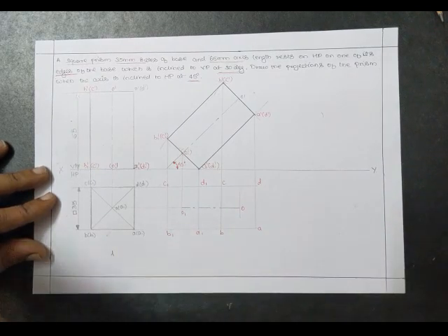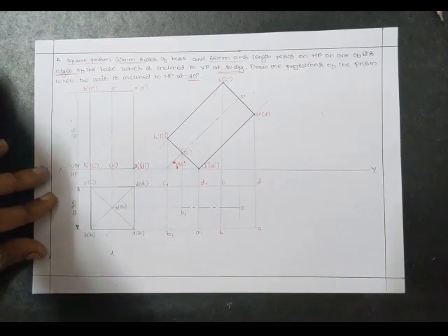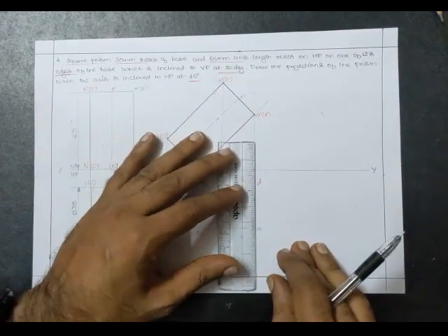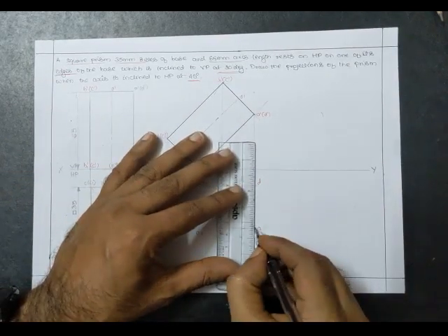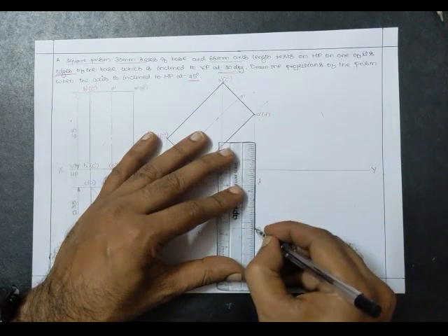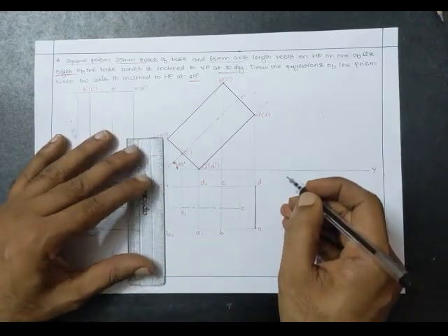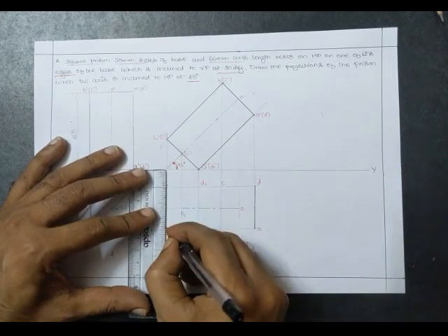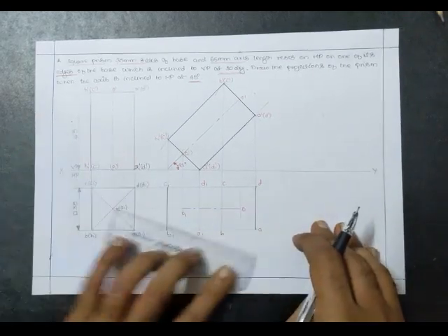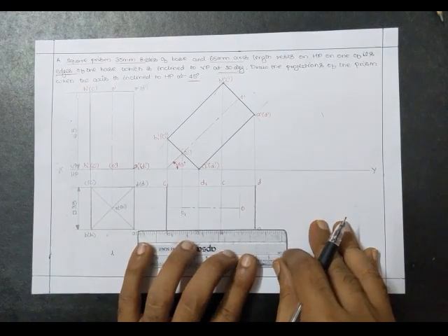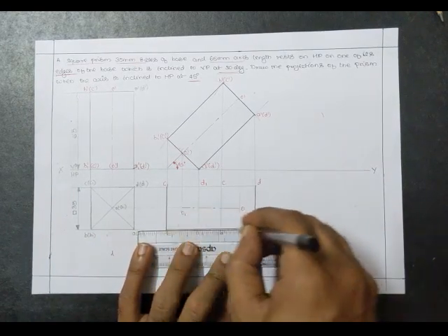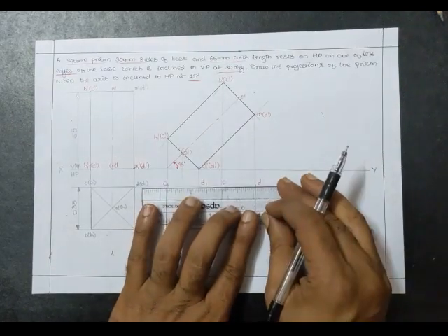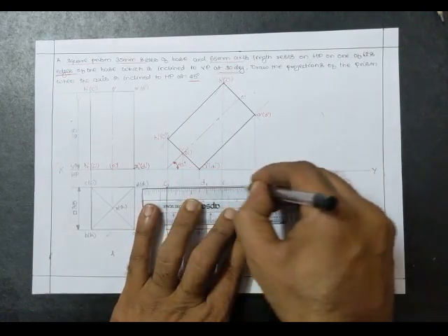Now let me apply the rule of projections. First I have to see the object which is visible and darken only that. The first and foremost step is that the outermost boundary should be darkened. So I am darkening only the outermost boundaries. There might be a slight variation in the projections, so make sure you work as per your projections.